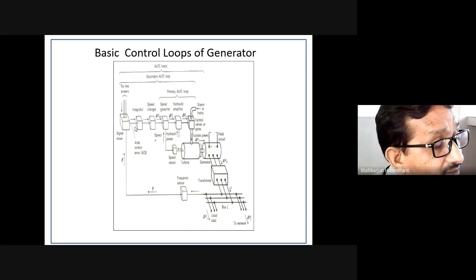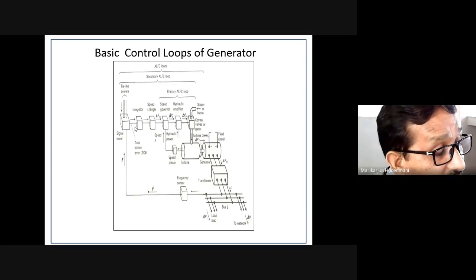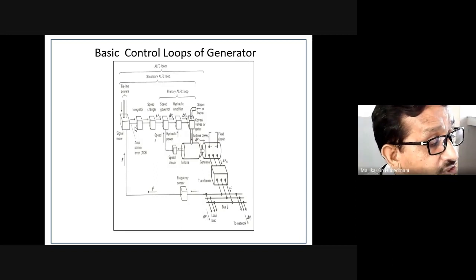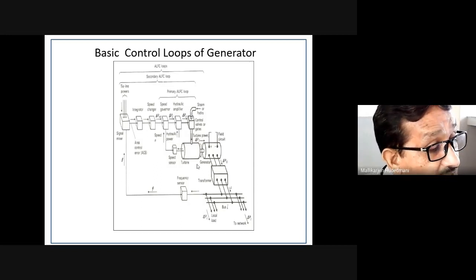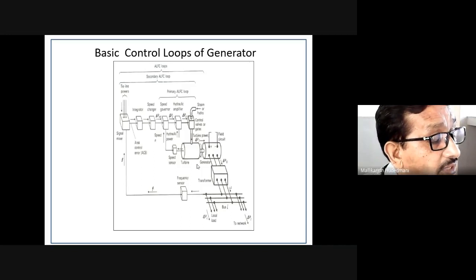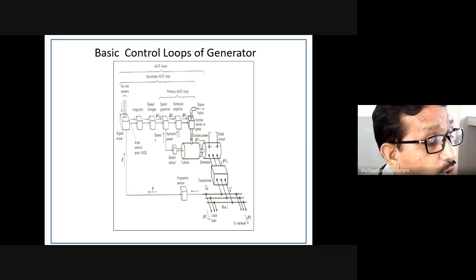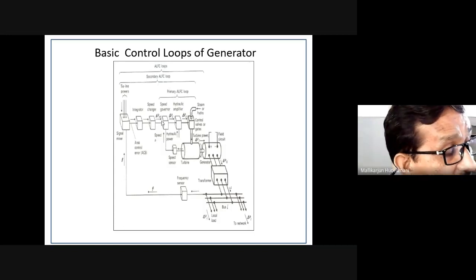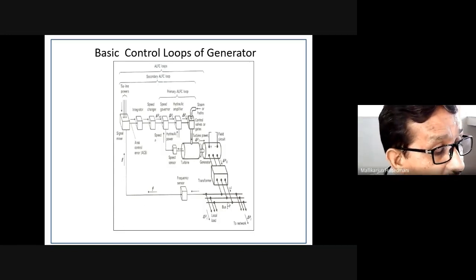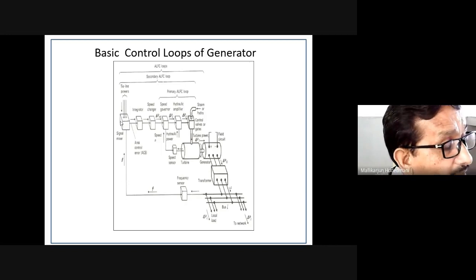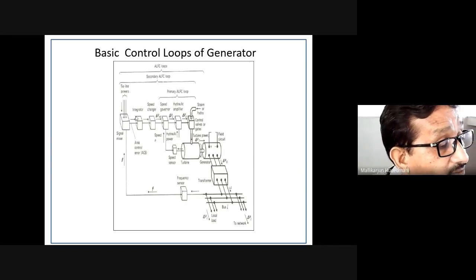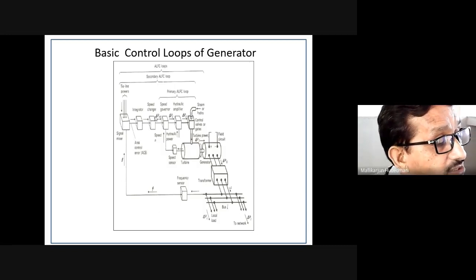But an electrical power system experiences turbulences and dynamic changes in the load, so it must be alert all the time, actively participating in the control. Therefore, we cannot say it is safe right now. Contingent changes have to be taken care of automatically: the error is processed by the PI controller, and its control output changes the speed setting on the governor.